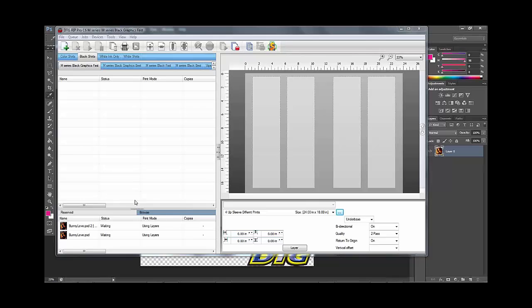I guess you really have to know more from your shirt manufacturer first off. The other thing is maybe a little bit more time might be needed on the heat press. And of course our general rule of thumb on the heat press for our curing and for our pre-treating process is 340 degrees Fahrenheit.